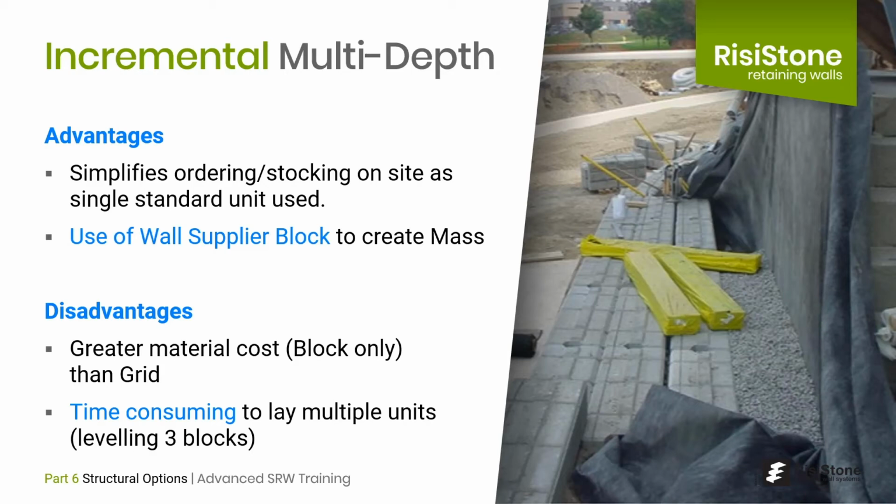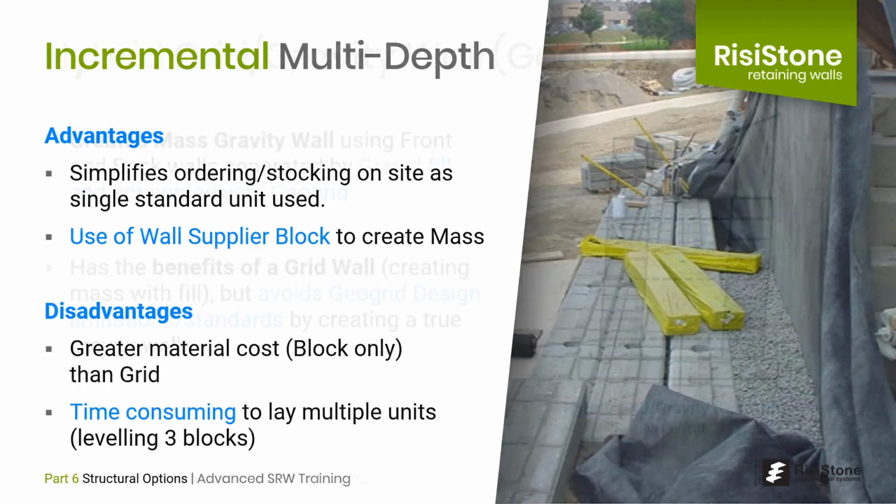The disadvantages of this approach are the fact that it would be more expensive than a typical geogrid reinforced wall, and it would be time consuming to lay multiple units back to back, particularly on the base course. Again, practically speaking, this type of structure would probably only work for walls that require 2 or 3 blocks in depth.